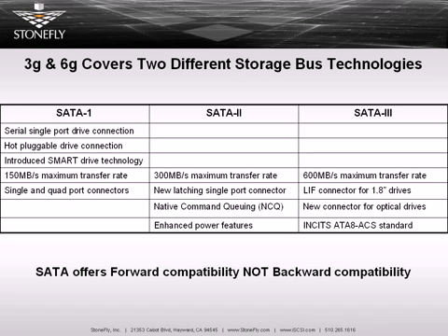We don't have wide cables anymore, and cooling was more efficient. The other thing is that the plug is hot pluggable. The ground connections are a little bit further forward, so when you slide a connector into the backplane, you get a ground reference and then you bring signals on. So we didn't have to have special drive sleds with intermediary connectors and so forth to take care of that.